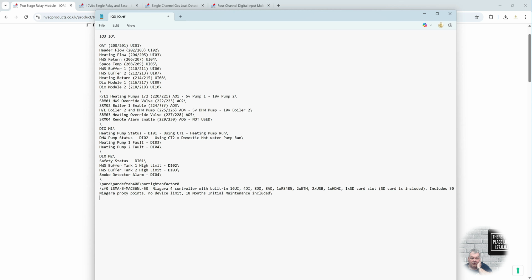So we've got the raise lower for heating pumps 1 and 2. That's normally binary, so I'm not too sure how that's configured, to be honest. But it doesn't make any difference. My software, I can select raise lower, or I can select binary if I want to. There's no problem. Or high and low with the software that I would write.